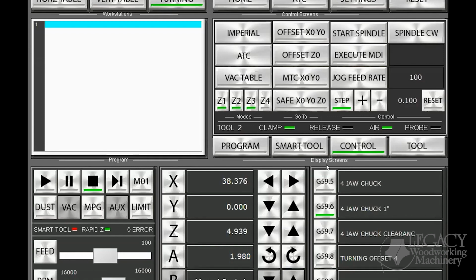Hey, Tracy, it appeared that at a 10th, it didn't move, or at one, your first two didn't move at all. Right, you're right. It didn't move the A-axis register, so it was too fine of a degree. And so I stepped all the way up to 1. I pushed this up to 1 degree and then it moved. And then I pushed it back to 1/10 of a degree and that worked. But if I push it down any farther, it's just too fine. It won't move at all.